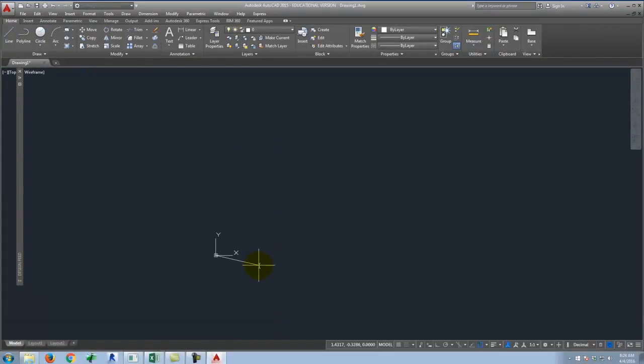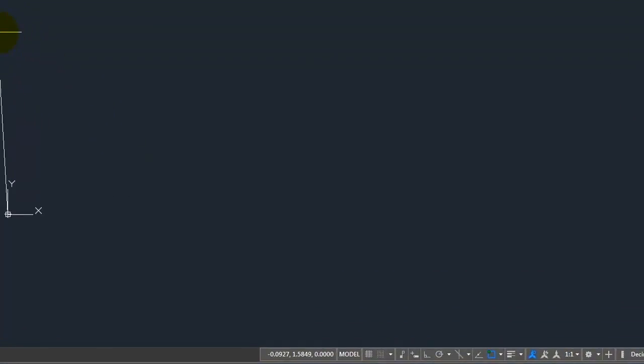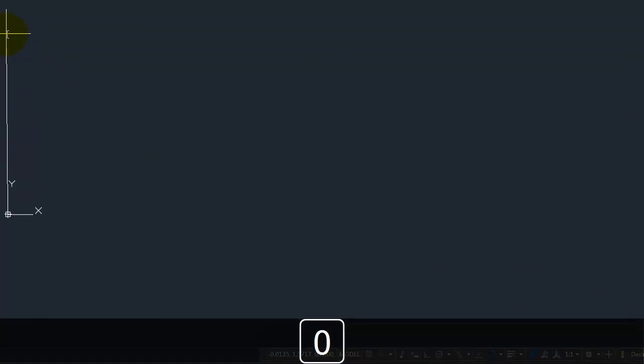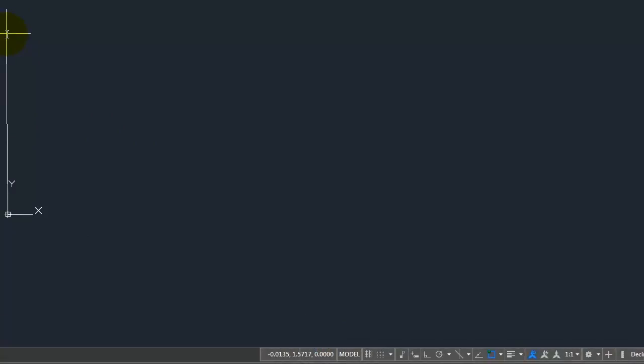And we can see the origin, I'm just zooming in and zooming out, as the cross between the x and the y. You can kind of see that right there in this little icon. Okay? The next point that I'm going to type in is I want a line that's 24 feet long along the y-axis, going straight up. So I would type in 0, 24, and I want to put the little apostrophe after 24 because that's going to indicate that it's 24 feet, not inches. The quotation mark is inches. The apostrophe is feet.